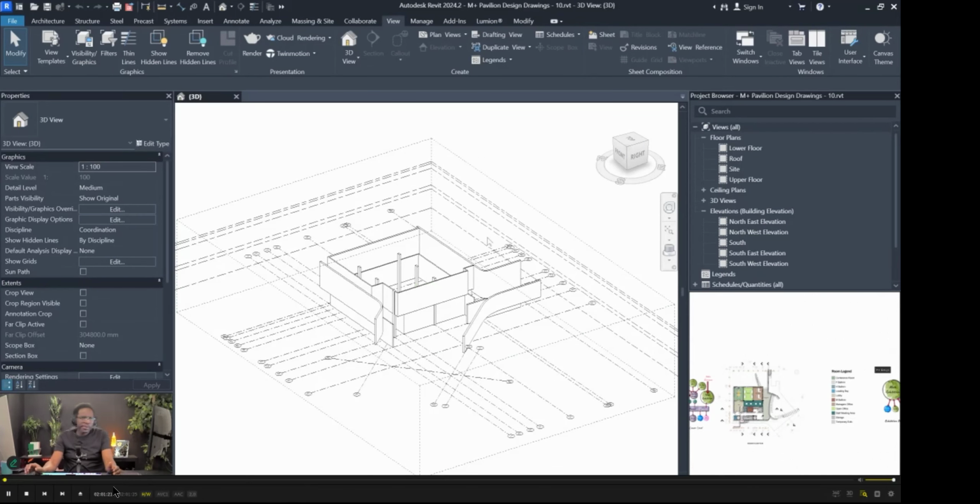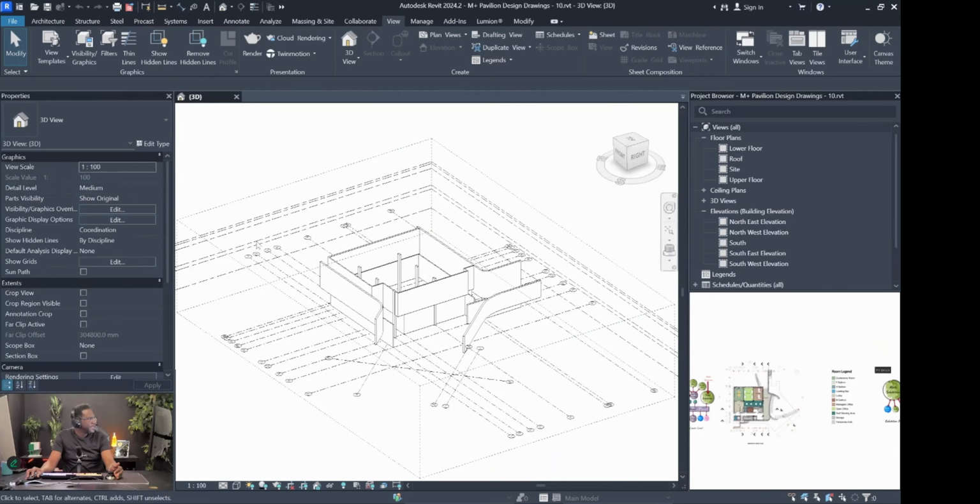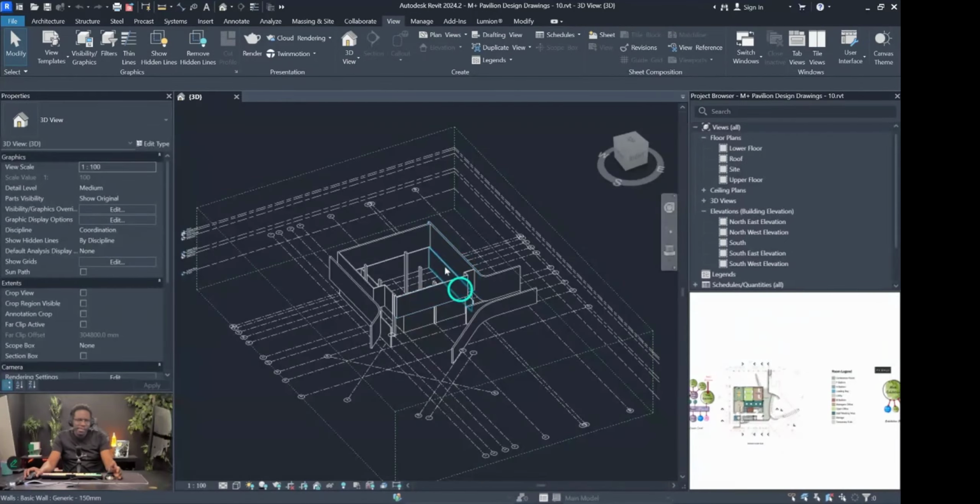Before we continue though, I'm going to make some user interface changes to make my process a little easier. The first thing I'm going to do is change to a black viewport. While modeling, it lets me see things in more detail. And then when I'm setting up the sheets, I'll change it back to white. So to change my viewport to black, I'm going to go to View, and then Canvas Theme and just click that. And yeah, now it's black, and it's a little bit more visible to me while I'm working.